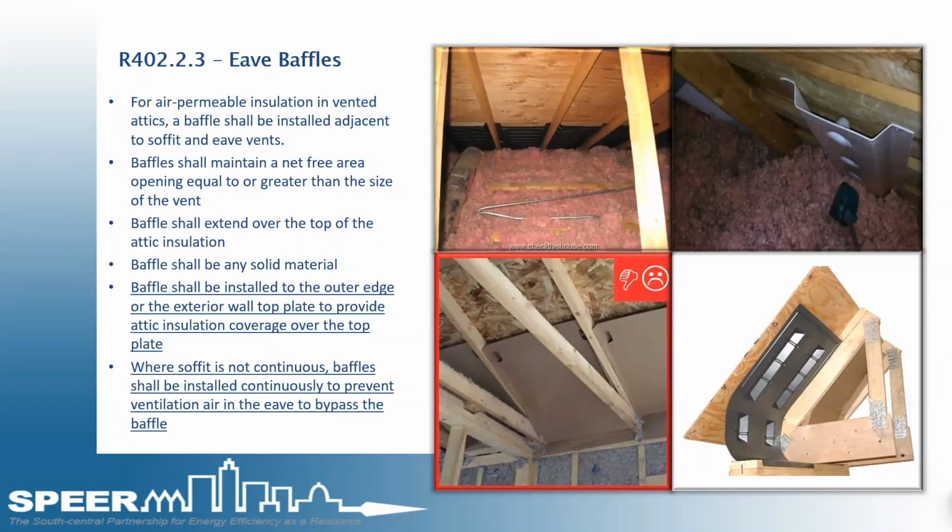Now the new code, I believe 2021, is stating that it's not just adjacent, it's got to be in every cavity in the ceiling, because they know that wind washes through there regardless of whether there's a vent or not. Baffles shall maintain a net-free opening for air to move through the attic itself. It must extend over the top of the attic insulation. They can be almost any solid material.